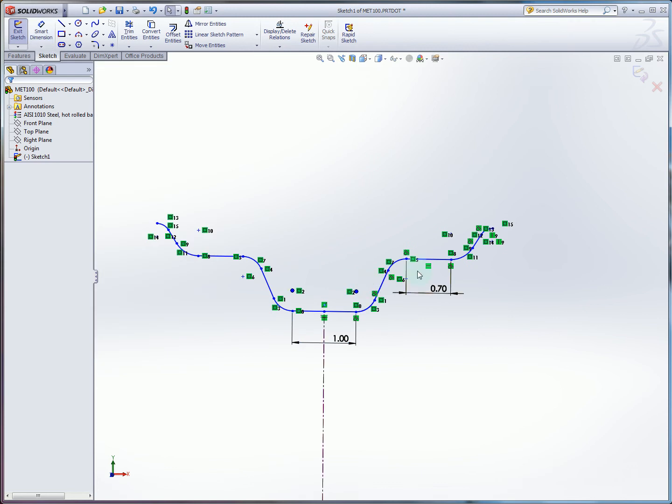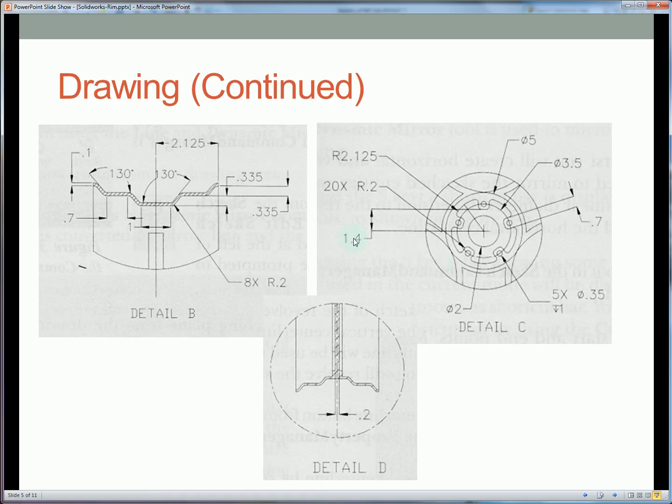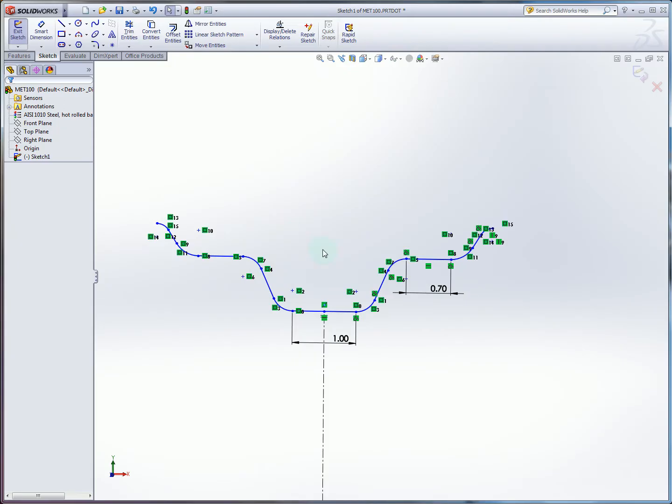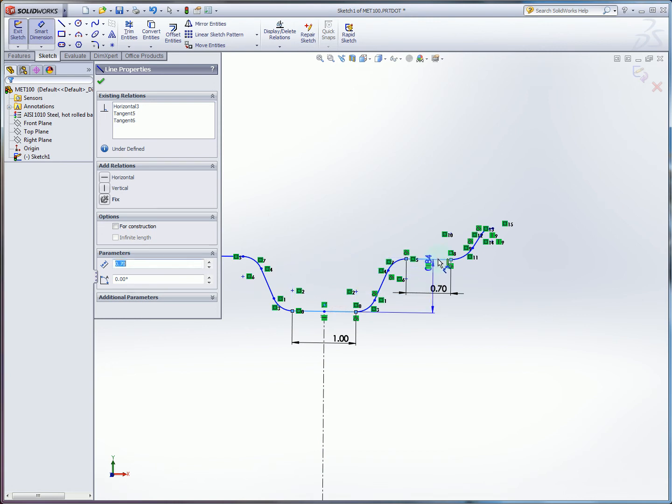Now the sketch hasn't fundamentally changed in shape, but we now have a few more constraints applied. Similarly, we can apply these height constraints. We have 0.335 each between the bottom edge, basically between each successive step. From our Smart Dimension tool again, we want to click on the bottom edge, select the upper edge here, and notice I've selected the edges, not the points.